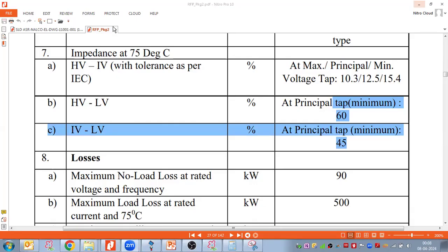One more question, sir. This DY11, if the vector group is changed, the DY1 transformer acts as a load. Can you please explain how it is acting as a load? Because of the voltage angle changing, it is acting as a load. There is one general concept that active power flows from the higher voltage angle to the lower voltage angle. So due to the voltage angle changing, it is acting as a load.